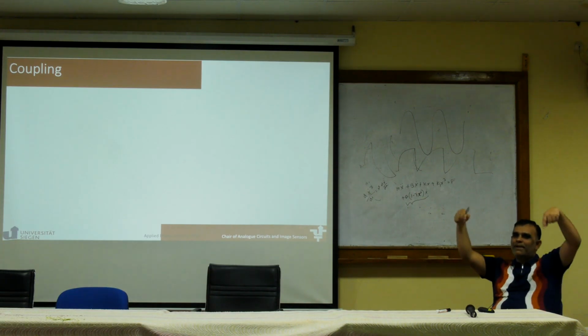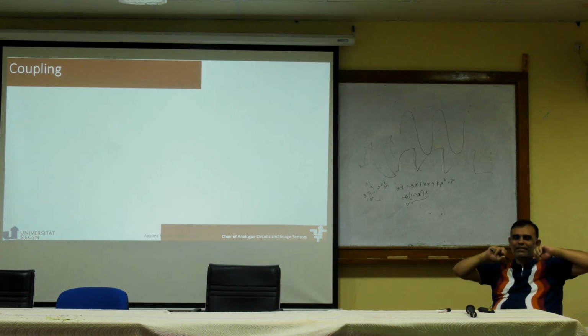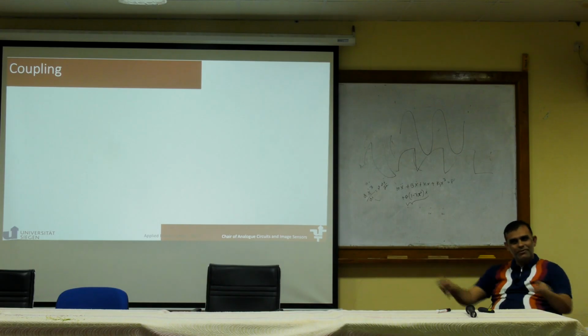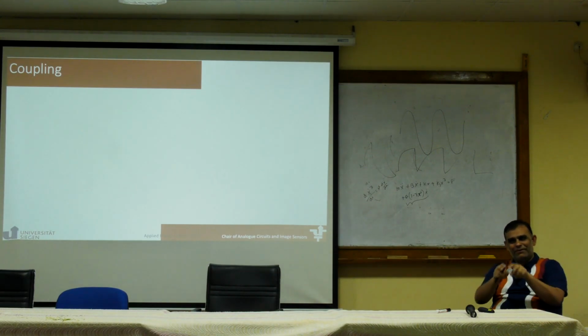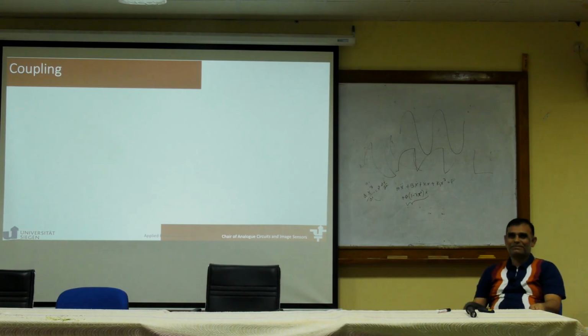So, if you take two pendulums and connect them with a string, there's only two ways the pendulums will move, whatever you do. They will either go together or they will go in opposite directions. You excite them here, you bring them here, leave them, after a few minutes that's the natural motion they will come in, as long as they are linear systems.